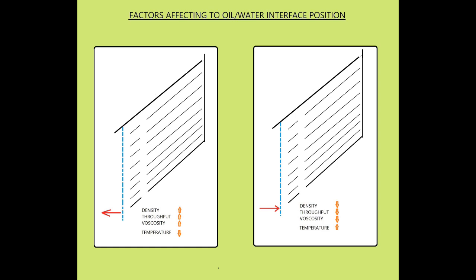If the oil-water interface moves towards disc stack more, there will be a risk of water escape with clean oil outlet. If the oil-water interface moves towards outer edge of top disc more, there will be a risk of oil escape with water outlet.